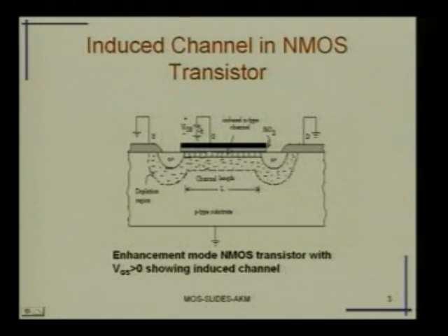We can apply a battery or some sort of voltage supply between the gate and source. For instance, the gate can be made positive with respect to the source, or negative with respect to the source. Similarly, we can apply a potential difference between the drain and the source. Since it is an N type, we would like VD to be positive with respect to the source.